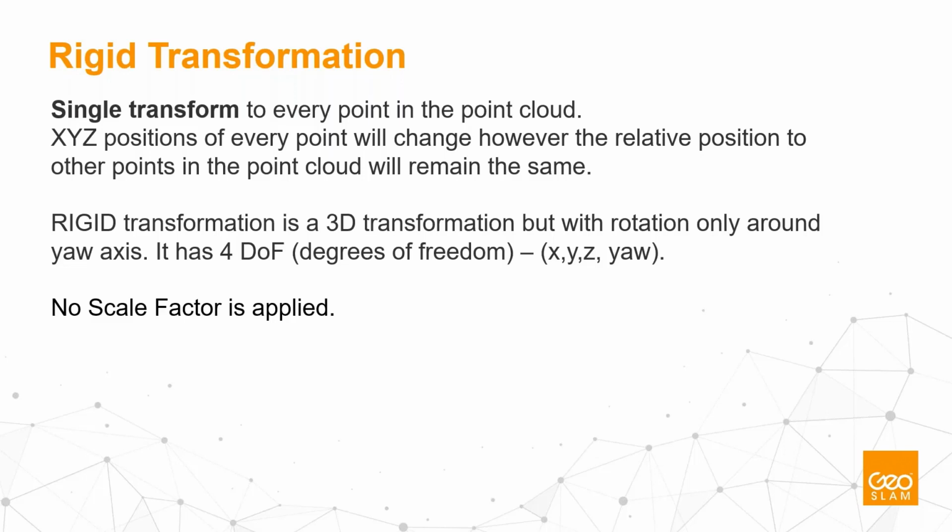It will move all of the point cloud, rotate and move it to the new position, but the relative positions within the point cloud will not change. So the sizes and the calculations within the point cloud will stay the same. It will just move the point cloud to fit the control points provided.